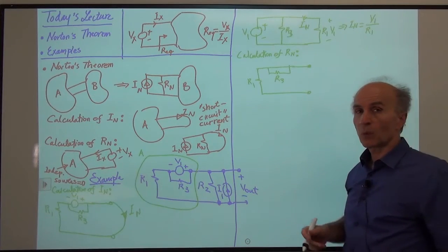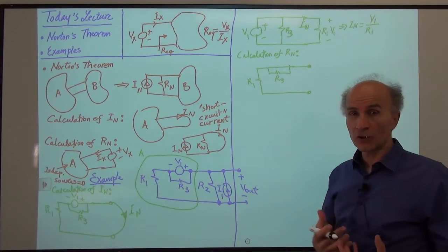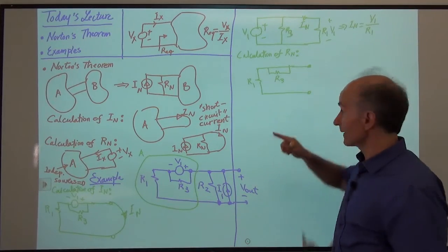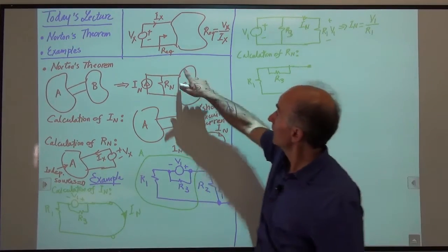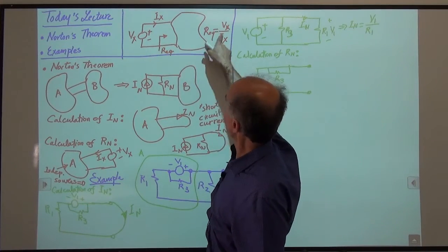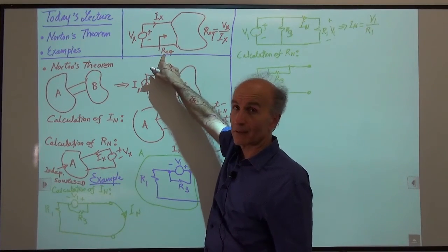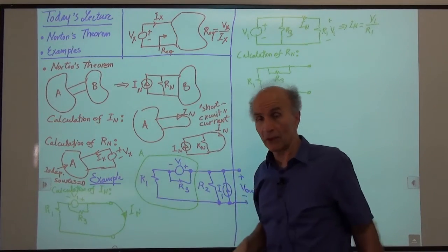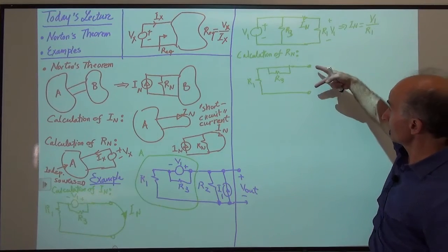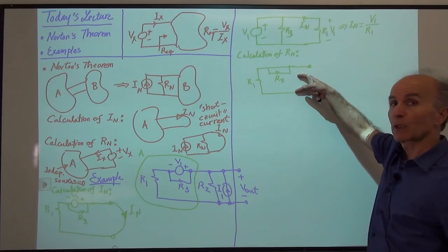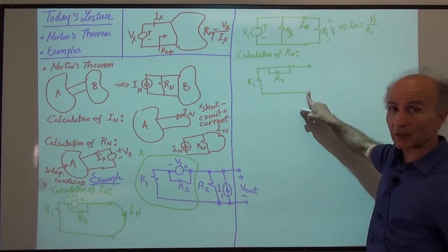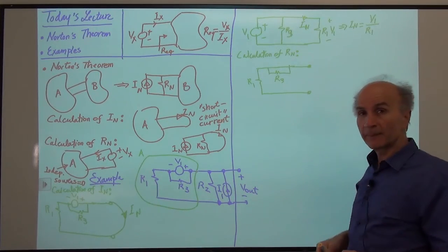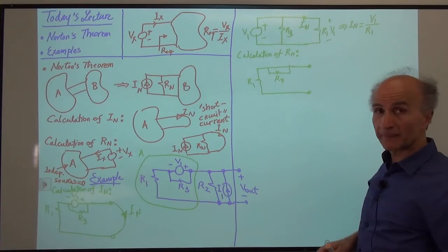Okay? So one thing that we say in our jargon is we see a resistance between these 2. So when we say the equivalent resistance is Vx over Ix here, sometimes we say the resistance that we see between these 2 wires is Eq. So the question is, how much resistance do I see between these 2? If you don't know, you can apply Vx and measure Ix, or apply a current source, measure the voltage. Either way, we can do that, but here it's very simple, right?